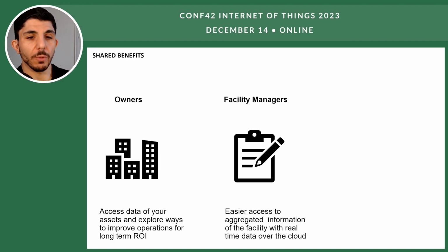Facility managers and equipment managers can understand the activity of the equipment at hand. For example, if you manage a school as a facility manager, you can figure out with some IoT connected devices like hygrometers if there's some kind of leak in the pipes. And instead of waiting until you have a flood in the hallways, you can get an alert, track it, and get ahead of the fix before there's any problems in school.